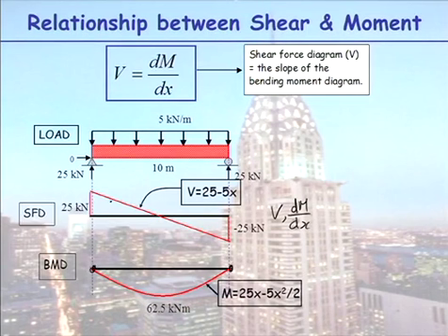My shear force is positive, that means it slopes down, then my shear force is negative, it slopes up. But this time round, the value is reducing. So what does that mean? It means the slope of my bending moment is reducing. And isn't that what it's doing now? It's a big value, it's getting smaller, and then my shear force, my slope is 0.